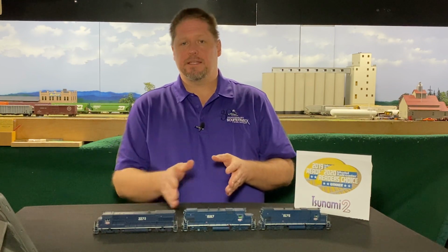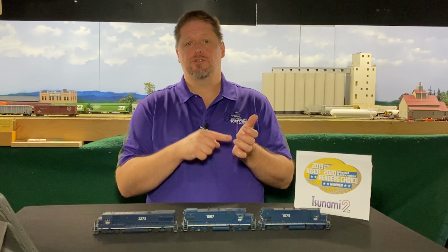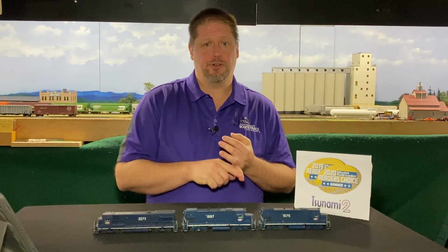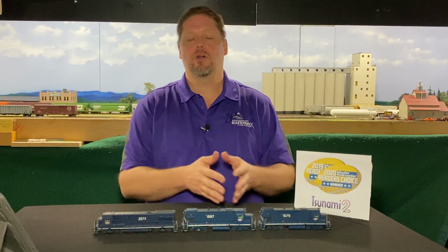So one of the things I always recommend is having consistent function mapping. And having consistent function mapping is going to make consisting diesels easy. So what that means is having every diesel locomotive in your roster have the same buttons do the same thing regardless of which locomotive you're controlling. Number one, it makes it easier for your operators, but number two, when you get into consisting, it's going to make it a lot easier and more fun. And again, consistent momentum rates and braking rates. That way every locomotive will run with every other one on your train, and your operators get a predictable idea of how long it's going to take for their trains to stop.